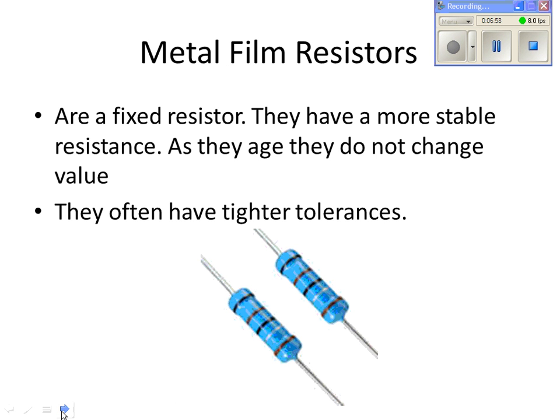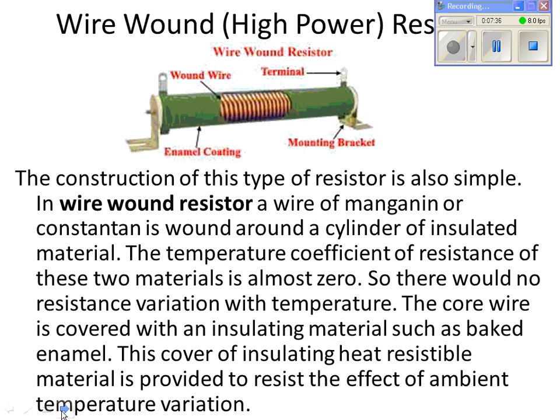And here we have a metal film resistor. You'll see them in the lab next semester. They're fairly common, and they're not quite as cheap as a carbon resistor. They're a little more stable as far as the resistance. They don't start diving in resistance as they get old, just because they're sitting around for a long time. Carbon resistors will just start losing some of their resistance or gaining resistance, one of the two. And a metal film is a little tighter resistance range, I should say.